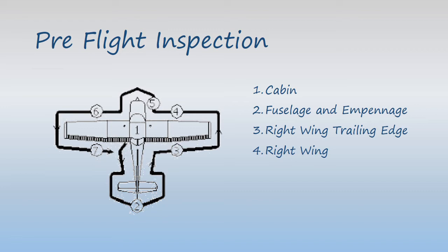Then you can do a manual check of your fuel quantity using your fuel stick. Check the main landing gear for tire creep and pressure, then the safety pin, the brake disc condition, and brake fluid leakage. Then you can proceed to the nose of the aircraft.